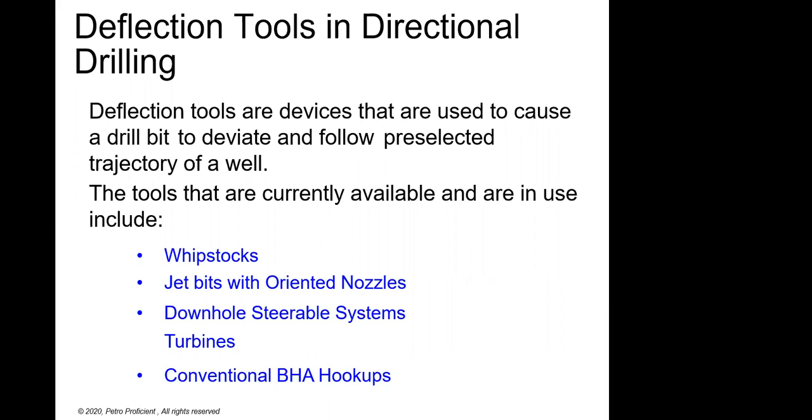You can have your BHA configured with your stabilizers in a way that when you apply certain weight on bit, the BHA will orient in one direction. So using stabilizer configuration, you can deviate. So there are some of the arrangements, but the most popular ones are the downhole steerable systems.